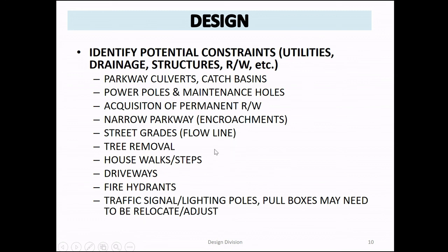There could be some trees that are in the way. This is also interesting because of the house walks, and when I say house walks, I mean house walks that are right behind the curb ramp. If you have house walks, make sure that you request a permit to enter, because if not, during construction, you'll have an issue, especially if you're doing case B or C.